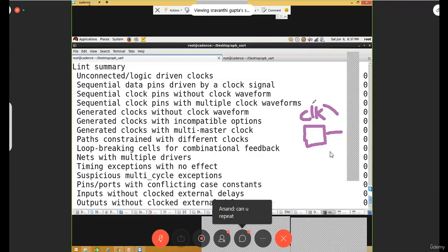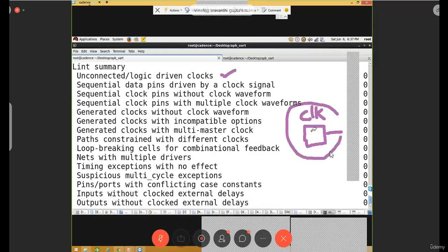Ma'am, I have one doubt. When we synthesize the RTL code, and you showed the window for the GUI, sometimes we get unmapped or partially mapped. What is that actually? Once optimized only, you can see the design is mapped. If it is partially mapped, that means there is some issue with your RTL code.